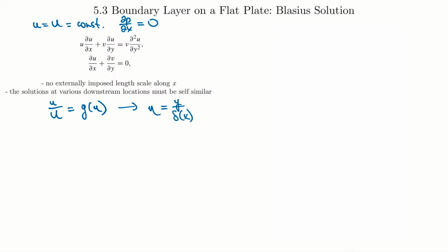In that case, we argued that the capital U parameter drops out of the equations if we scaled the velocity, lowercase u over U, and considered that as the dependent variable. And then we had that was a function of y and time and nu. And our dimensional analysis showed that we had that functional form u over U equals, and then we had capital F as a function of y over delta.